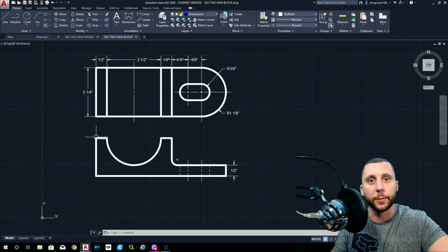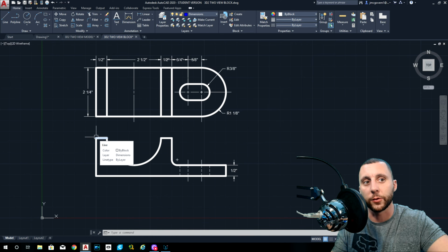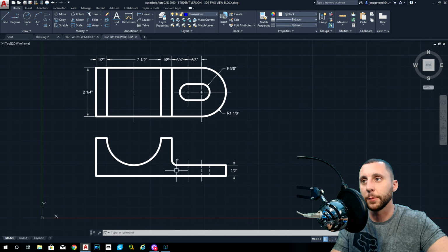So what I'm going to do is head back to this corner after I did that 0.5, and I'm going to go 0.5. You can see the diameter of this circle is 2.5, so I can't quite do that yet, but I can go 0.5, 2.5, 0.5, and come down. And wherever this line comes in and that one comes down, where they meet is going to be that corner, and that's going to be a fillet radius 1/4.